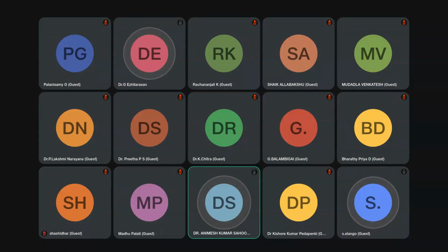In primary control, mostly it is to implement the local controller, like power sharing between different PV inverters with different battery energy storage. Secondary control we use mostly to deal with the frequency and voltage magnitude deviations as a result of any kind of power sharing happening in the microgrid. And particularly in the third layer, which is a slower controller action, we do different kinds of energy management studies like demand response, balance, and all these things.